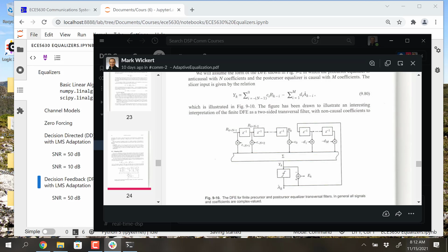Okay. So compared to the regular linear equalizer, which has all of those z to the minus 1 blocks with the coefficients tapped off of the input signal, which is the continuous time or sampled versions of the continuous time received signal following the matched filter, the decision feedback equalizer only puts taps for the so-called precursor coefficients. So you're going to sit ahead of the main pulse, and then the C0 there is the main pulse in the interference pattern. And then the post-cursor is managed by the decision feedback terms, which come out of what this